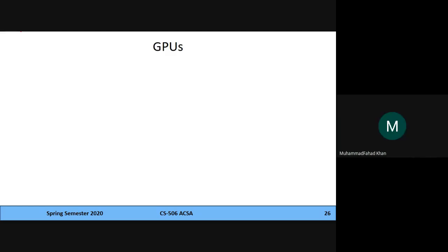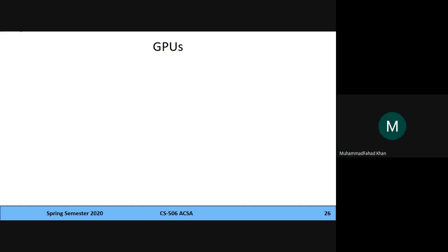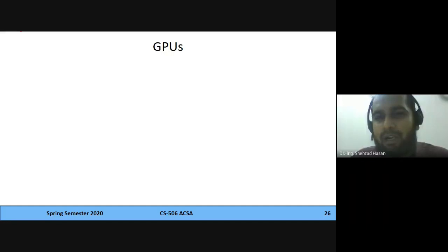For example, if you were talking about multiplication, we have discussed those multiplication operations, the Booth's algorithm, and radix 4 Booth's algorithm. You just have to go through that table, select that particular number, do the multiplication, and verify the results. For division, the first thing I told you was to check for overflows. If there are overflows, then you don't continue with that. There was an overflow, and still you started with the division operation. Except for I think one student, everyone completed that part.